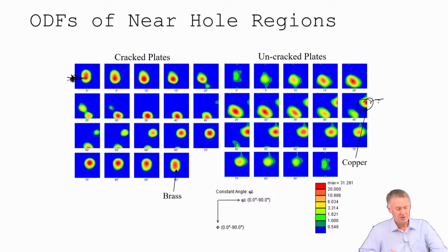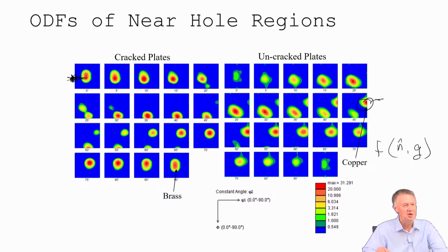Anyway, so that took us right back to copper by looking at grain boundaries. So this is one of the functions that I mentioned in that first slide, where the function is in orientation, right? So that's the function we looked at. It took us back to texture. It was familiar enough that we knew how to change the process. So we ended up changing the process. And they actually patented this to say this is a way to stop hole expansion cracking.